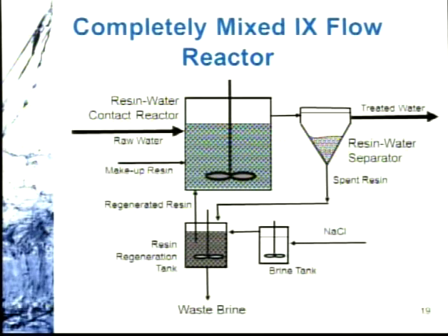The difference here is that the resin is not regenerated in the primary treatment path. So here water comes in on the left, goes through the CSTR, resin's recovered, and treated water goes out the back end. The resin is removed physically from this process and regenerated outside of the primary treatment process.